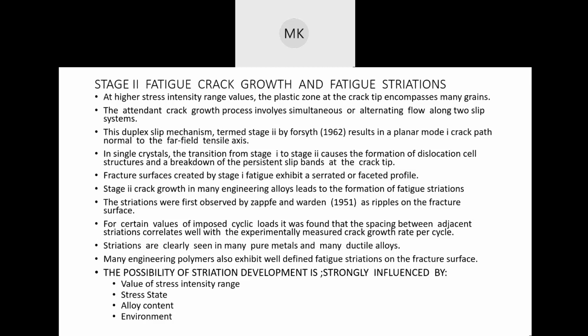The environment plays a very, very important role, and the way you can find out whether oxide is getting formed is when you see a fracture surface and you start seeing a cloudy image on the surface. That's when you know that there is some form of oxide generated on the surface. That oxide can just be because of the failure and the material being in the environment. So generally after you finish the test, you take the fracture surface, blow air on it, clean it, and then look at it under the microscope.